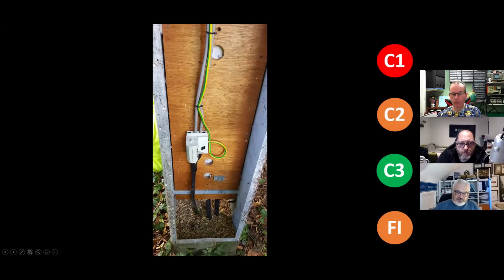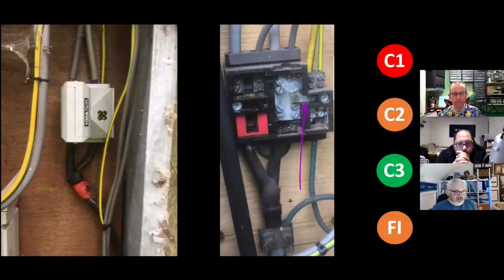I was desperately trying to find more of, but yeah, so that was the after of reporting it to the DNO and them coming out and someone competent going, yes, that should be enclosed within an insulated cutout, a GRP one. They're not plastic, they're GRP. So yeah, I thought that was a great example of an after. This is an interesting one. I don't know why there are two pictures. So it's probably me screwing up here, but let's just look at the picture on the right.